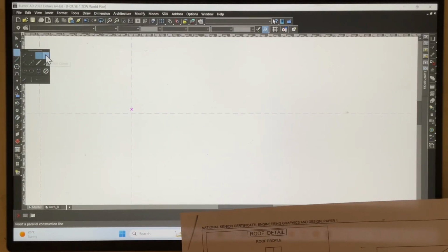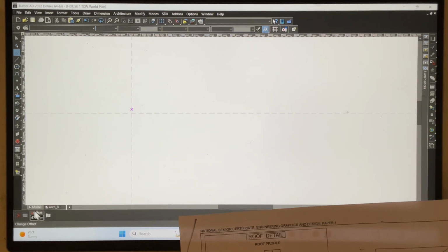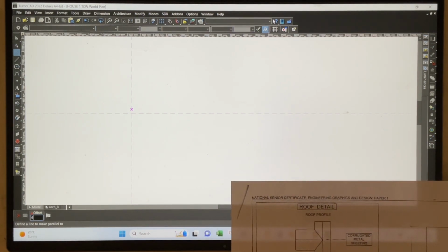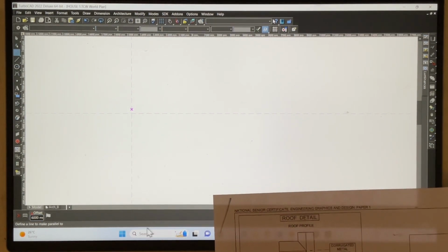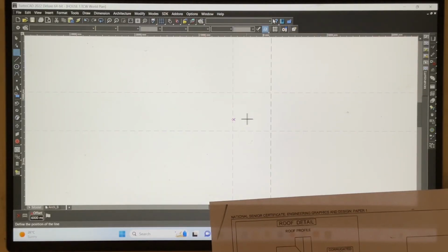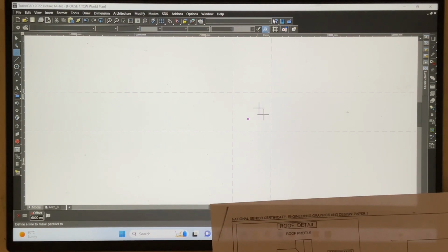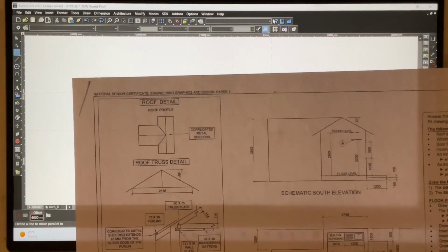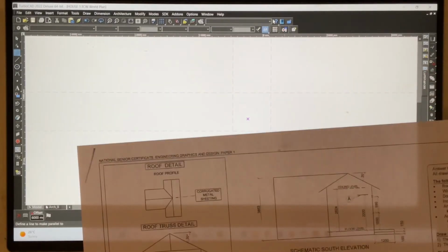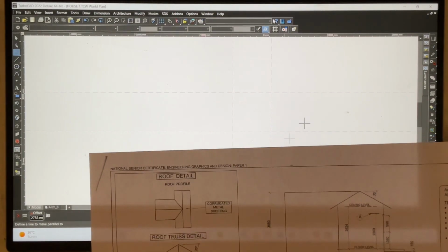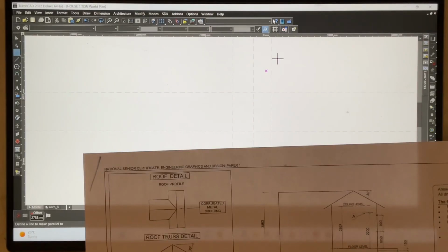You've got the parallel construction lines, so that little lock at the bottom over here, and you press tab, that highlights that little block at the bottom, and you go 6,000. Press enter, and click over there, and click over there, and you can see you've got the square with 6,000 that way, 6,000 that way. It then says that I need to go 2758 across, so I go tab, 2758 across, and I click over there, I click over there.